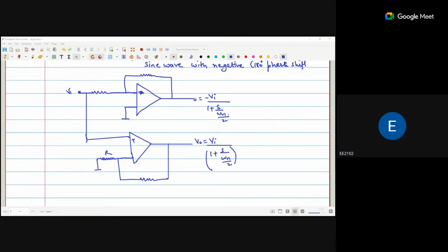So that is the main concept related to week 7. Except this one, I think there are third order filters also. But we already saw that if we go with the higher order, our system can become unstable. The stability will depend on the gain, how much gain you provide in the filter. So that is similar to the second order; you can solve that with the help of the second order. That is the main important thing related to week 7.